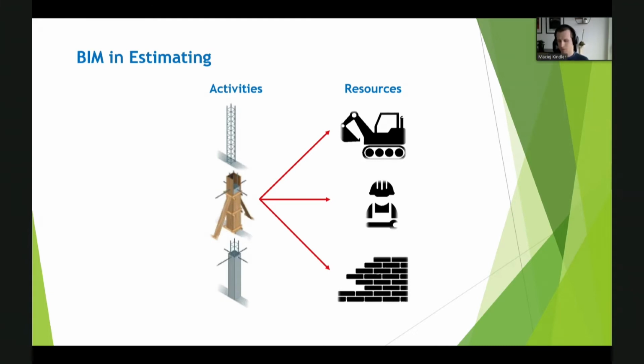But because it comes from multiple drawings, it's usually done by more than one person, so there is a difficulty in bringing structure into it. Putting BIM up front gives you a structured input coming from BIM objects that can trigger recipes that provide a consistent list of activities for a certain type of works, like precast structures, steel installation, in situ, excavations, piling, any kind of finishings, which then could be fully resourced also in a semi or fully automated way.